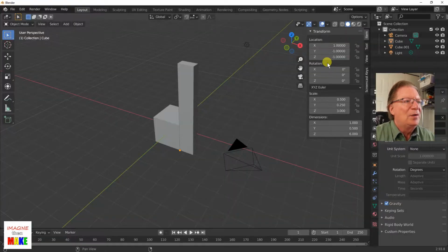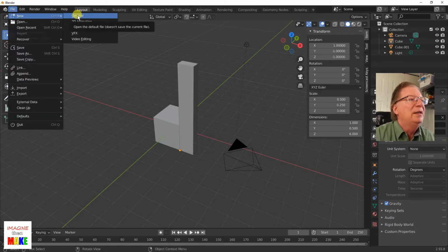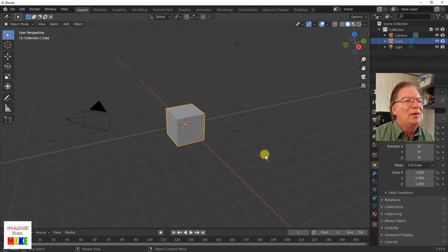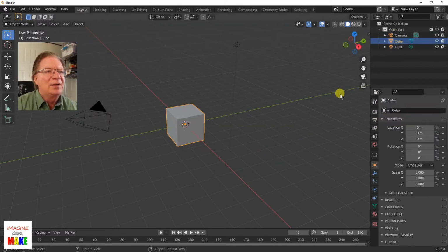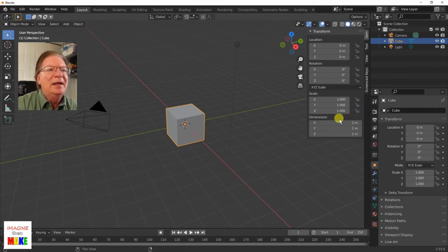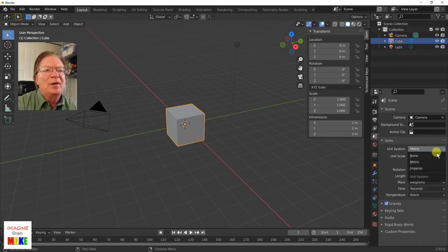So let's switch back over to Blender. We're going to start a new scene. I'm not going to save what I've already got. Here we have the same 3 familiar objects. I'm going to start with the first cube and press the N key on my keyboard. We're going to change our units again. Let's go back to None, to try and stay consistent with our LibreCAD drawing.